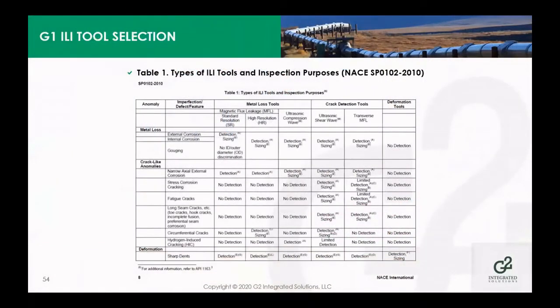And the NACE standard practice SP0102 provides a great help with this table. Gives you anomaly types and the available tools to categorize your defects.